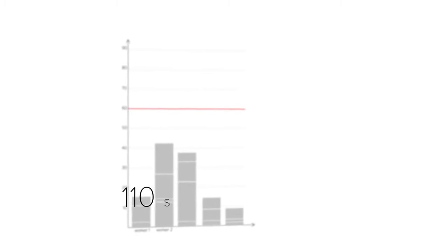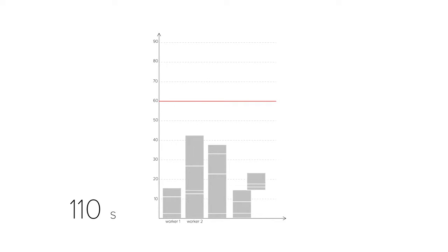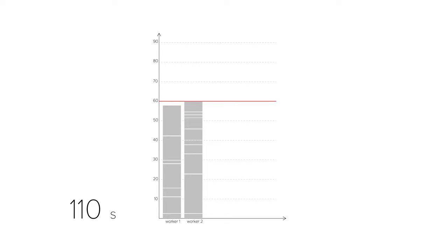The remaining assembly time of 110 seconds per piece divided by the customer tact of 60 seconds generates the required demand of 1.83 workers. Rounded up, 2 operators are needed in this case. The required workload can then be distributed equally between the 2 operators without the customer tact being exceeded. Thereby, the chronological priority relationships between single elements need to be taken into consideration. For example, the packaging of the product can only be carried out after the assembly is completed.